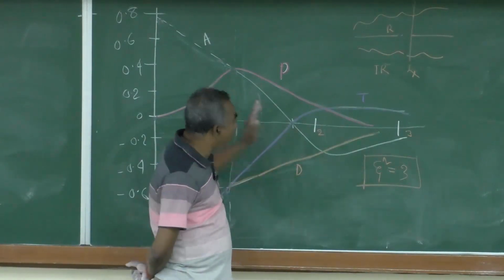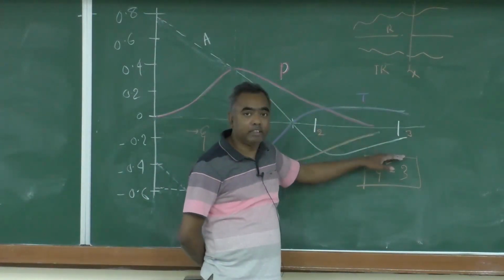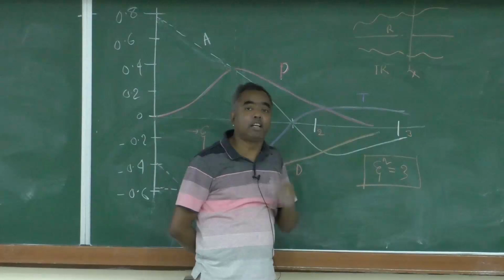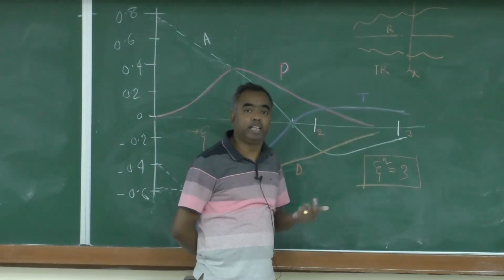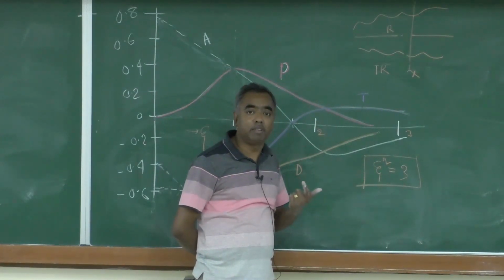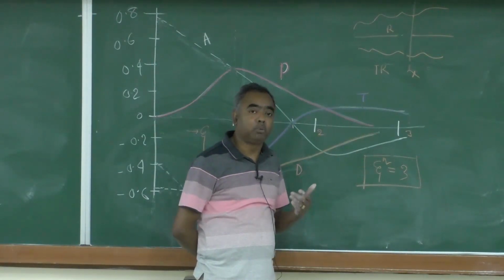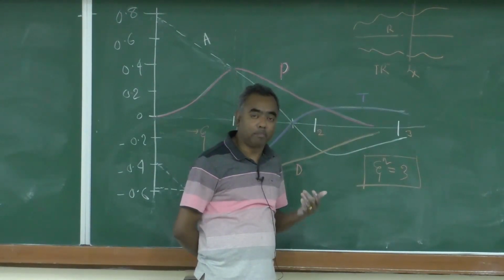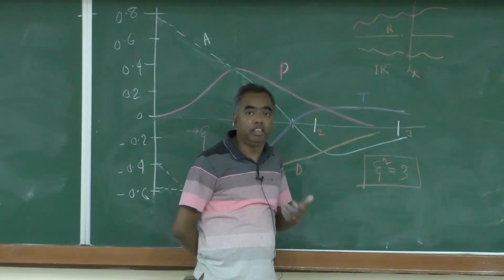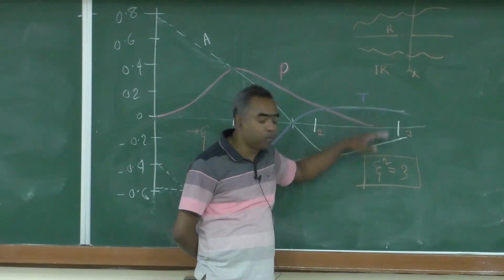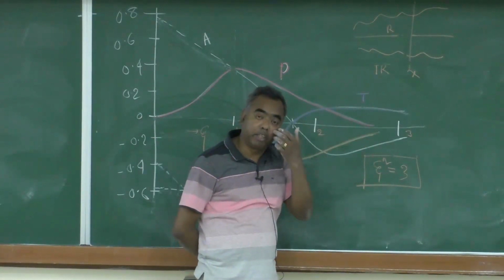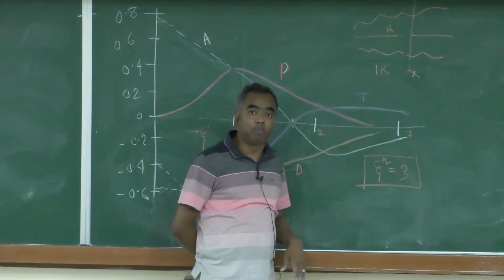But for an accurate case we have to consider the intermittency function, because as we said in the previous class, intermittency is 1 around the central line, but it does not become 1 towards the outer side of the wake. That means you need a correction near the outer side. So, there will be some deviation with respect to the actual experimental observation.